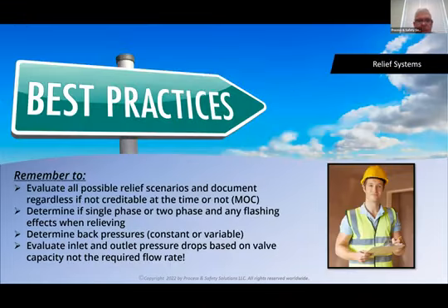So I tried to cover most of the scenarios that we see in terms of sizing and back pressures and errors that are typically made. One of the things to keep in mind is always evaluate all possible relief scenarios and document them, regardless of whether they are credible at the time or not. Remember, it may not be credible, like we talked about the blocked in case, or the pump feeding it may not overcome that at this present time, but by documenting it, we have that information in the future should we make any changes to the system then.